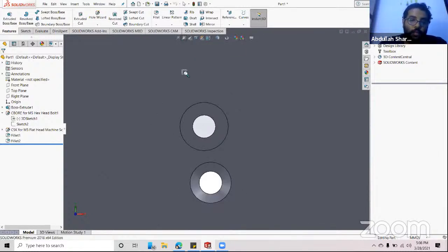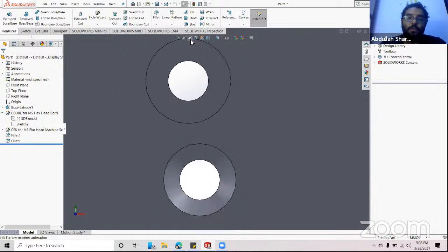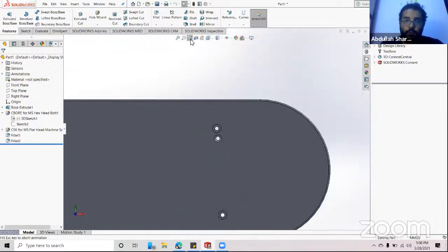Previous view, as I told you, we can make another zoom in. Then I will select this, my previous view, and this is my previous of all previous views. So I can go back each time. It's like Control Z. When you do something and you do Control Z, it will take you one step behind. This one is for the view. If you have a view and you come closer as zoom in or zooming out, and you want to go to the same point of the view that you were before, you can just select zoom out.